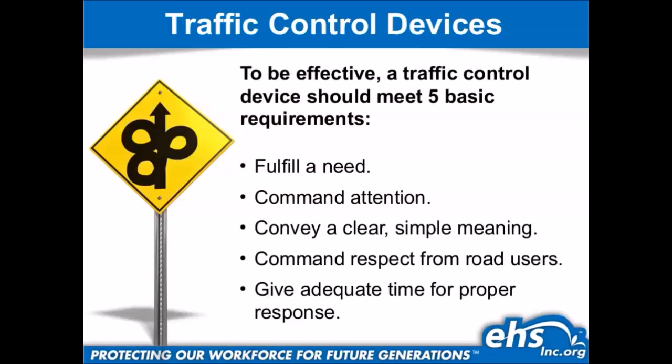It must command attention. Now, signs, yes, people look at signs for the message, but what draws your attention in is the bright colors, right? Or the blinking lights or the waving flags. So your devices must command attention. Must convey a clear, simple meaning. So that means they should be easily understood. Must command respect from road users and give adequate time for proper response.